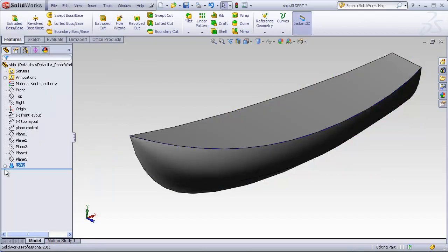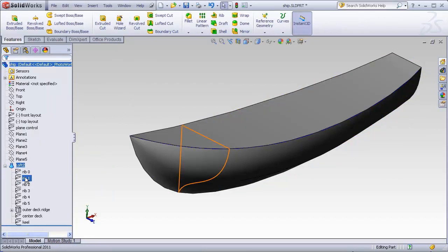One of the things that we see here on the completed loft, if we click on the plus sign, is all the separate pieces that went into making it become absorbed into the loft features. So even though these had to be created ahead of time, they now look like they're actually occurring later in time than the actual loft creation. This is one slightly confusing thing about SolidWorks, is that things that came earlier, once they get absorbed into a feature, look like they're coming later. But these, of course, in order to be absorbed into the loft, had to be created before the loft could be created.